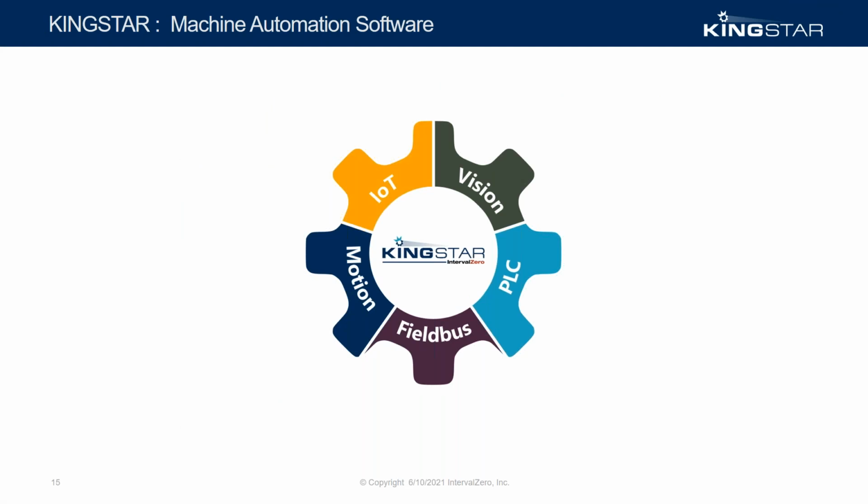Kingstar is based on 5 different products. We have the Fieldbus, which is based on a real-time operating system and the EtherCAT master, the motion control, the software PLC, vision, and IoT. Kingstar runs on the 64-bit version of the real-time extension RTX of Interval Zero. It allows applications to be developed in real time with C++ in Visual Studio and on the Windows side with any development environment. It can be used on a wide range of computers from 2 to 64 cores, and it is deployed in many different industries such as robotics and automation, but also medical, defense, and simulators.